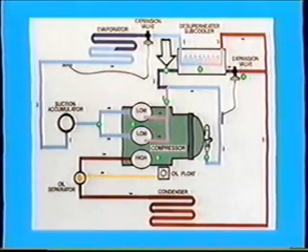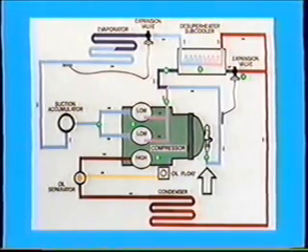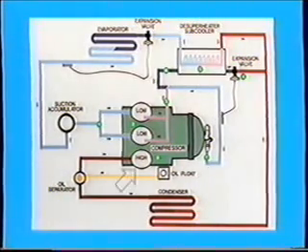Cool suction gas at interstage pressure flows from the heat exchanger to the intermediate manifold, where it is mixed with the refrigerant leaving the low-stage cylinders. This mixing de-superheats the intermediate stage refrigerant. De-superheated refrigerant at intermediate pressure flows to the motor compartment and then through internal passages to the high-stage cylinder bank. High-stage cylinders compress the refrigerant and discharge it to the condenser.